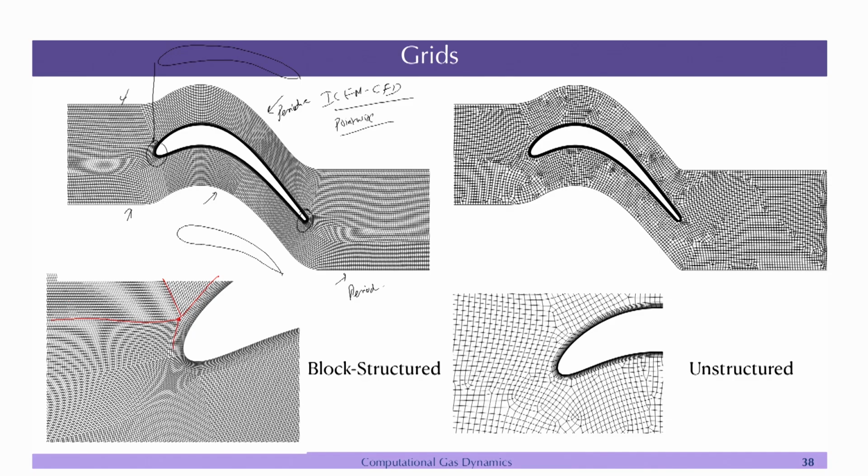Very close to the body there is a single block, which is actually not a single block. We basically have the boundary layer, which is very close to the body, aligned to the geometry that we have. This is what I was saying, that it is very important that you respect the curvature on the body. If you want to make a flow past a cylinder, you cannot make a grid which is going like this and this and this very close to the body. If you make it, there will be a lot of errors.